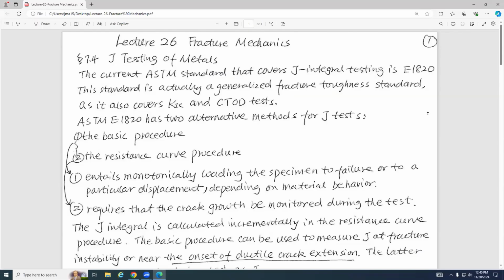Whenever you buy some materials, you will always check these two to know what the toughness is, and how much energy the material can absorb before it fractures. GIC and KIC are the most important concepts in fracture mechanics, so I will test your understanding of this.